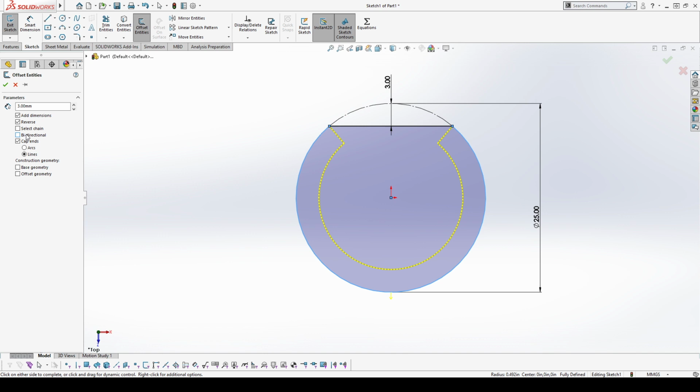That's why I said I'm just going to use this as a demonstration tool rather than to actually use it. Remember, we want to offset the geometry inside, but there are times where you'll just draw a line or maybe a spline. You just want to offset it to give it some thickness, and then you want to cap the ends. You don't want to take that extra step of going in and drawing a couple of lines, because if you're doing that a lot, it saves you time in the long run.